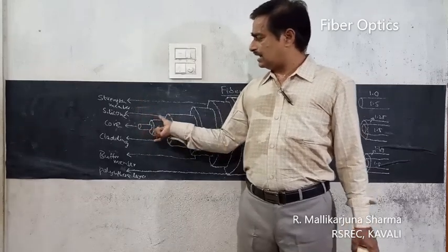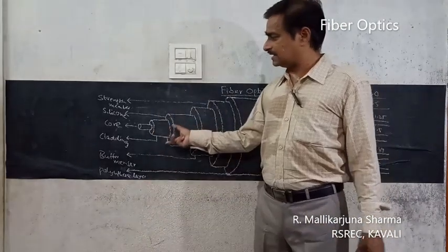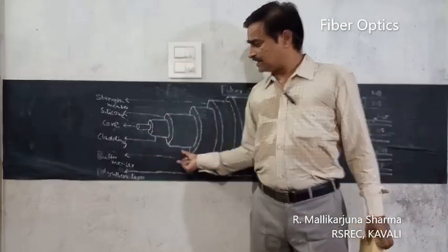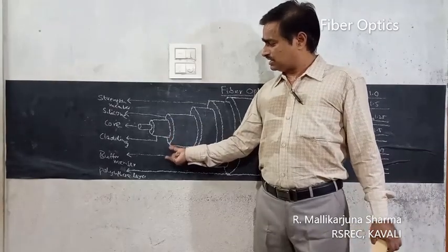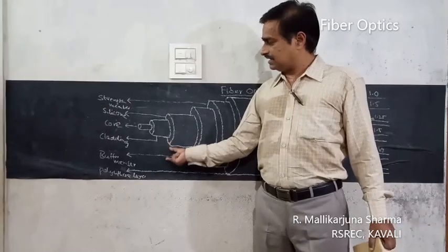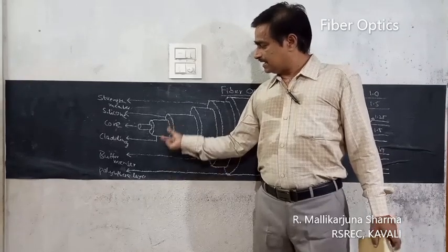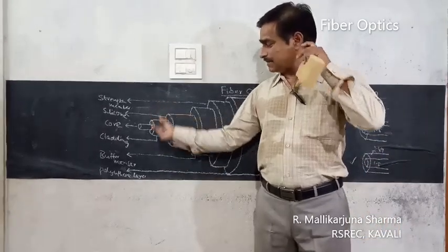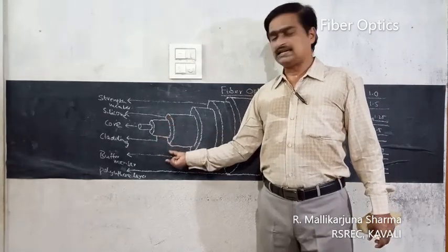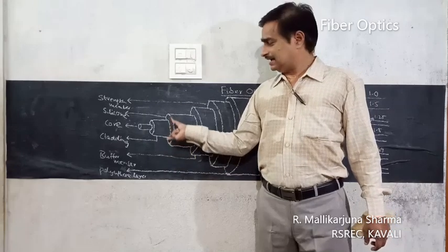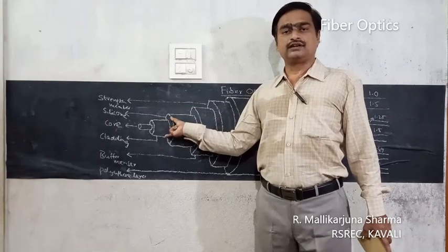These three structures are only about the propagation of light, and the material is brittle. Then next comes the buffer member. It acts as a strength member, and its refractive index is somewhat better. It is an intermediate member between the strength member and these delicate parts. To some extent it has hardness, and its refractive index is in between the strength member and the silicone coating.